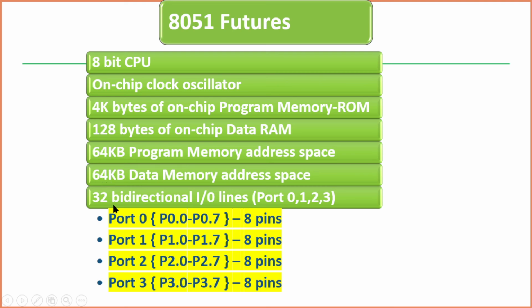Then we have 32 bidirectional I/O lines, which are organized as 4 I/O ports, each 8-bit wide. All are bidirectional. We can configure either input or output. Input means we need to write logic 1 on the port bus or latch.